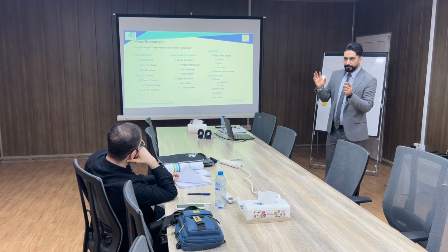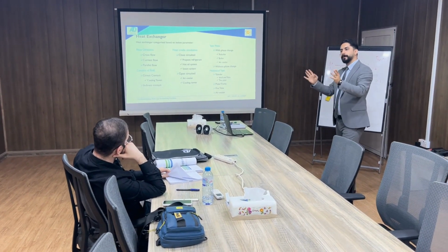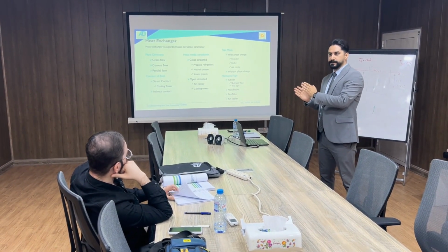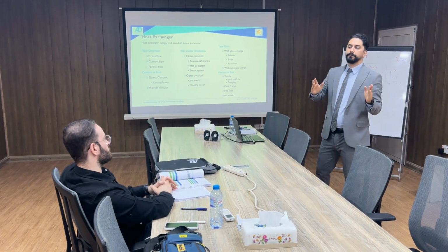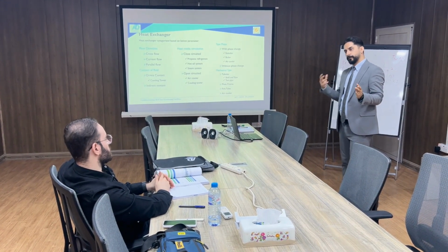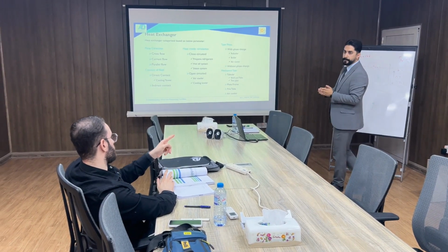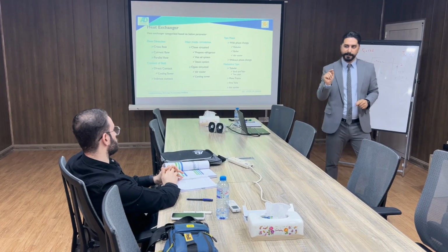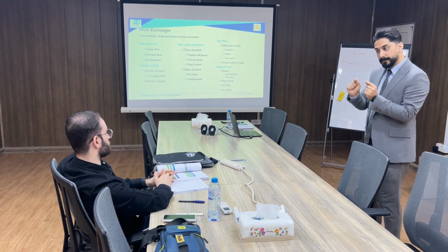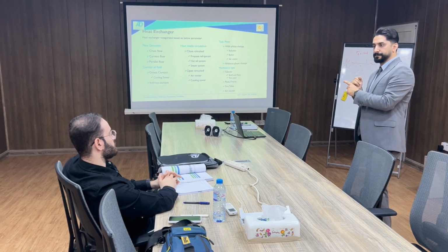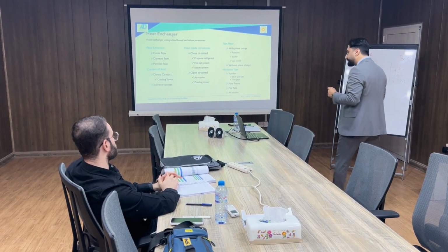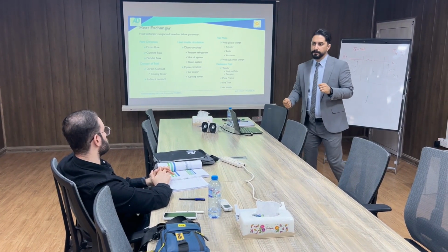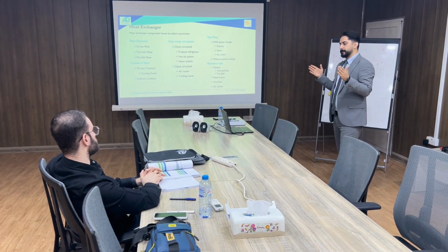Okay? You remember the formulas? In all of conduction, convection, and radiation, the temperature difference and surface area were the most important items for choosing the best one. I think here in this slide there is no surface area. In cross flow, it depends. It depends on the design and of course the fluids. Okay? In plate type heat exchangers, in most cases they use counterflow because they want to use all the surface area available.